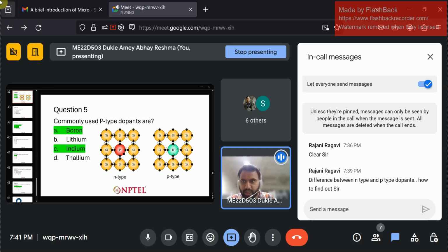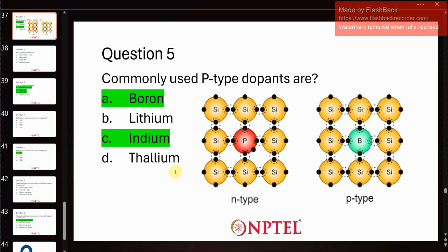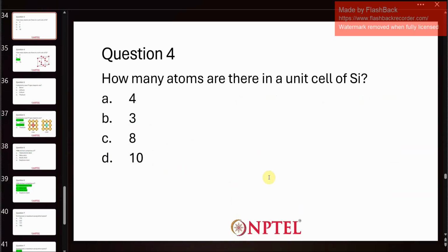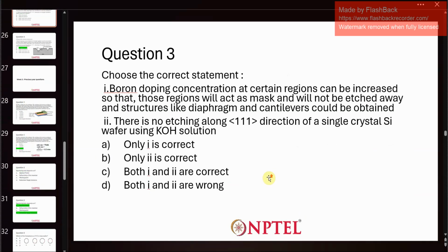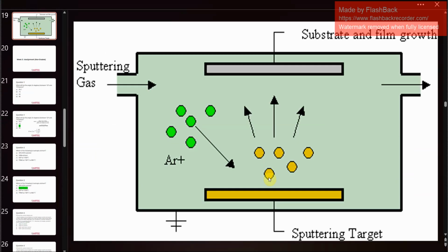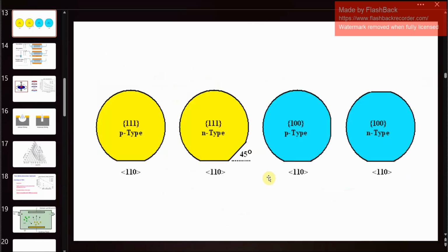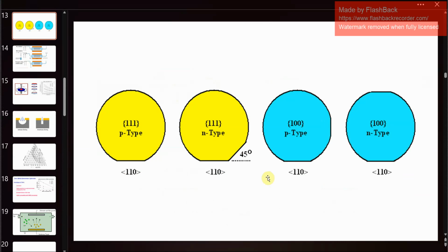And if you want to identify the wafer, you need to design your own strategy. My strategy is: for P type 111 it is flat. Then N type 111, I say, is 4 o'clock, then P type 100 is 3 o'clock, and N type 100 is 12 o'clock.